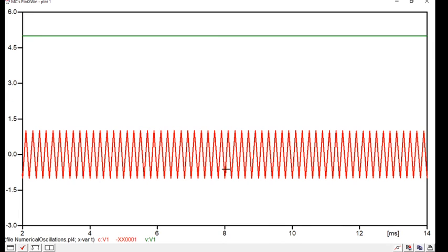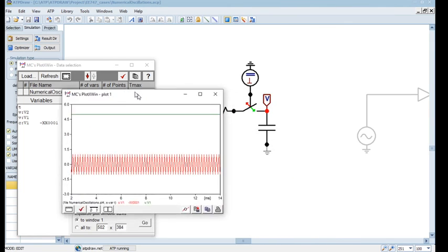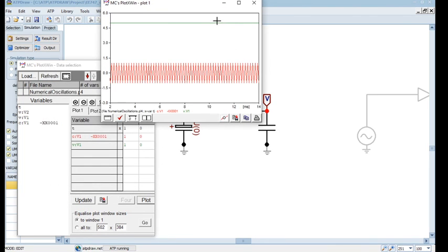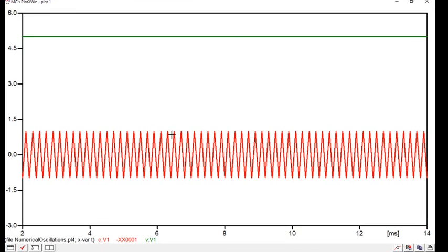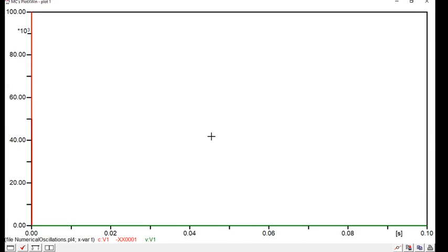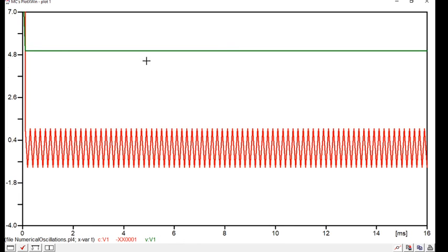See, again it depends on how you model it, and since we have used a switch which pertains to some other block module of ATP, it introduces some modeling differences from our program. So what happens is, in the voltage, if you see, there will be a chattering effect. Let me zoom in. Sorry to put it like this, but it's really visible in the current waveshapes.